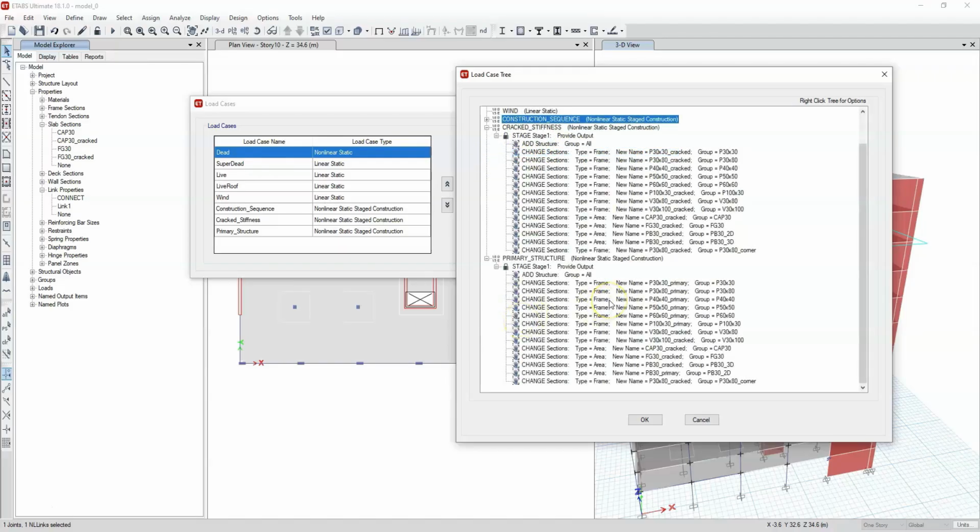That is to say, we have 2 models. The first model we call the global model for seismic analysis. It is a model where, through stiffness modifiers, we set the entire structure to 50% stiffness. It does not matter if they are secondary elements or primary elements. All elements are set to 50% stiffness in accordance with what the Eurocode requires for reductions in bending and shear.